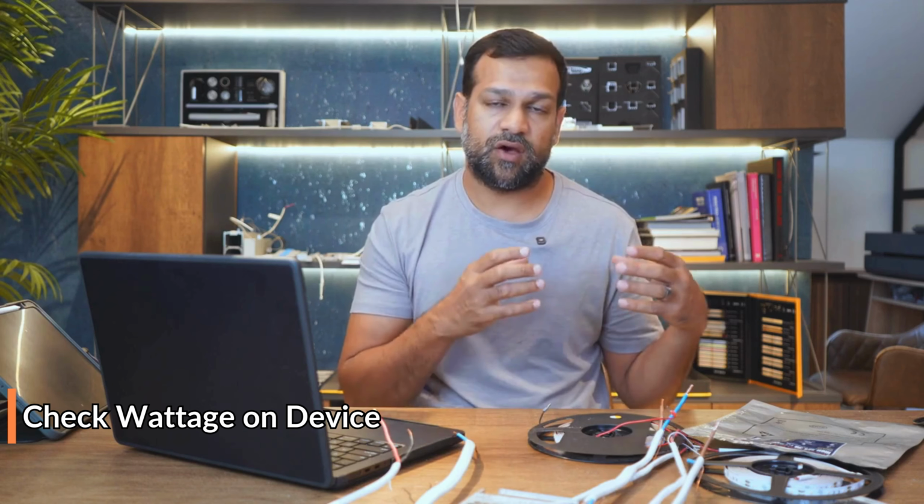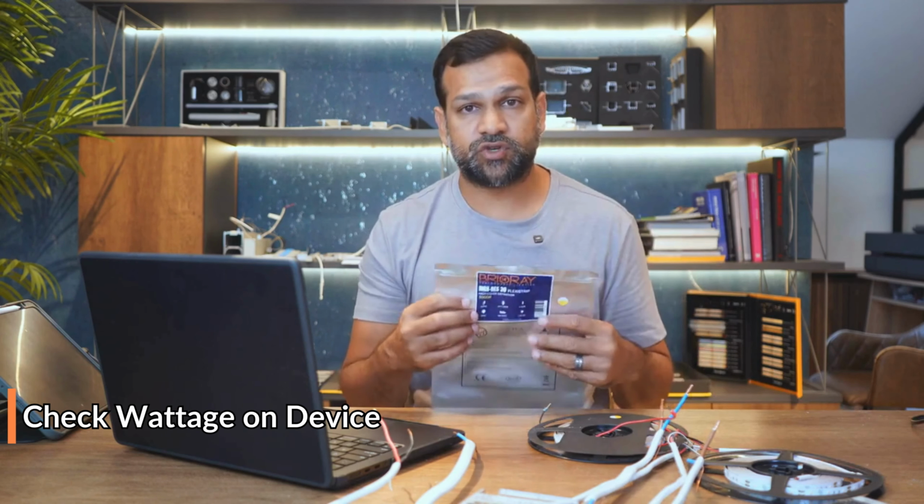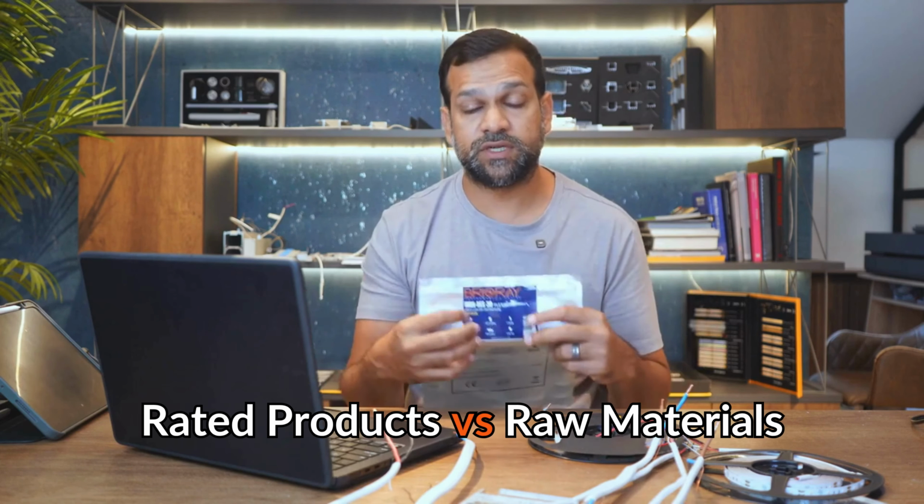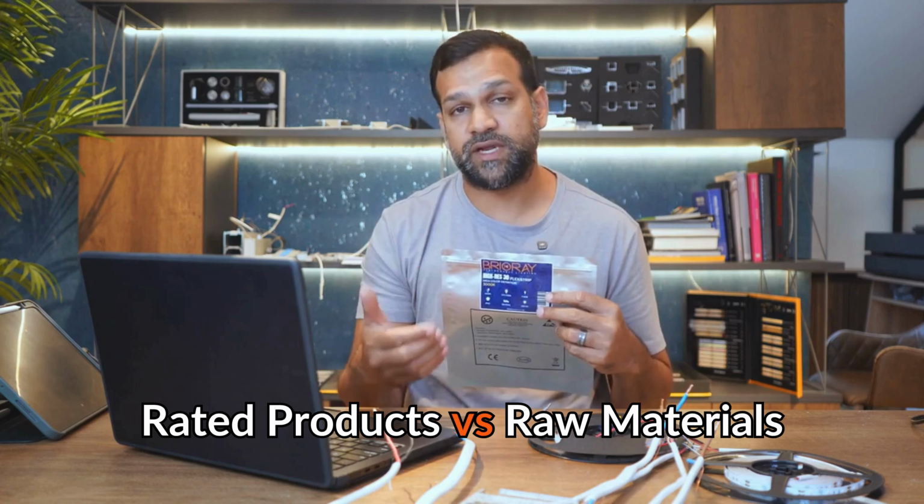So that's the basic formula that you need to understand for calculating the total power of an LED linear system. If you're using bulbs or any other LED product, the wattage would be listed on the device itself. Prefabricated linear strips should be rated, but if you're dealing with raw material, you need to understand what the power rating is per foot or per meter, and then you simply apply it into the formula. P is equal to VI, so power is equal to voltage by the amperage, and that's it. You're going to get the total power consumption needed for your LED linear install. So let's look at the other calculations.